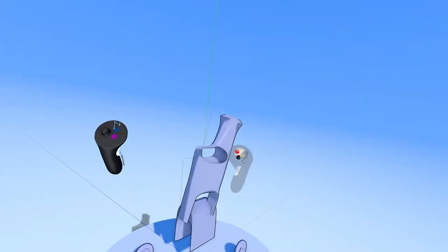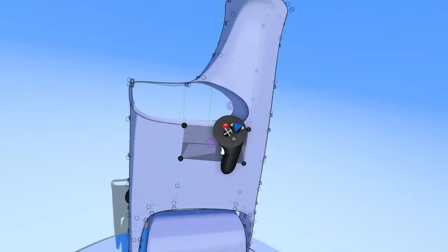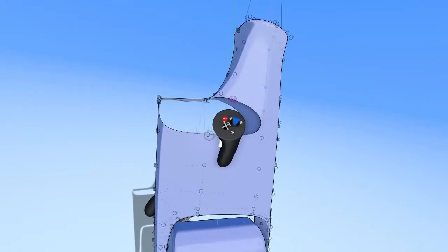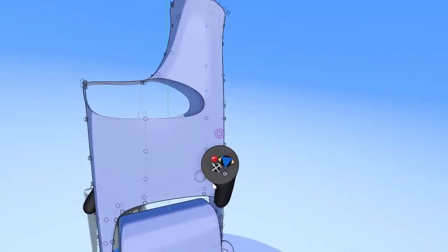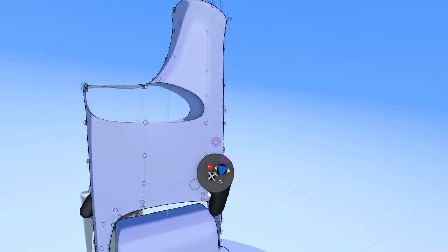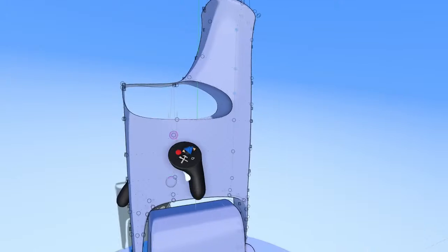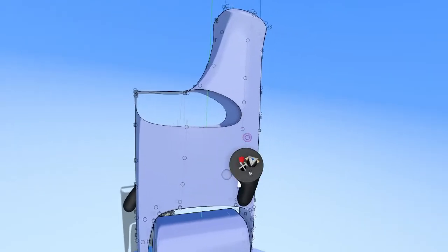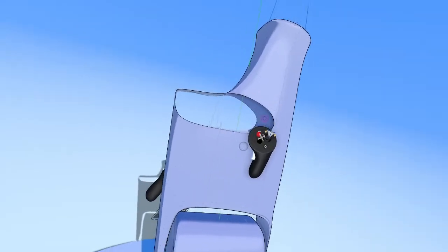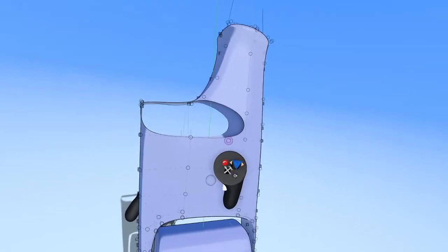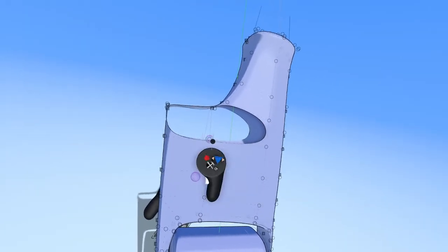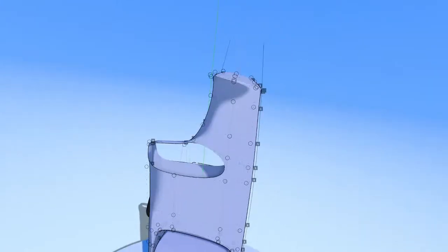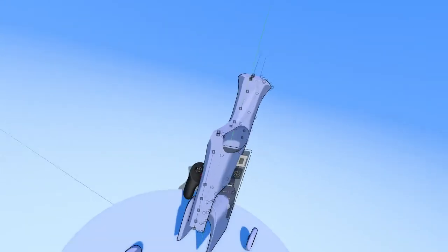If I take a piece of sub-D geometry and put that into edit mode, of course I'm looking here and I can select all the different options here. I can select faces, edges, edit points, but if we look at our right-hand joystick right here, we have this icon. It's kind of this blue pyramid, and that's going to visualize the different options that you can select. So if I swing that to the right on the joystick, I can select only edit points. Flick it to the right one more time, only edges. One more time, only faces. And then the fourth time, or the last time, is all of the options here. I usually leave it in all options. That just seems to be easier for me.